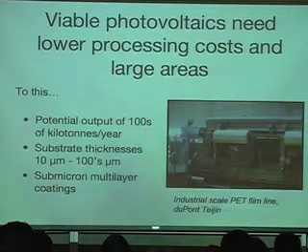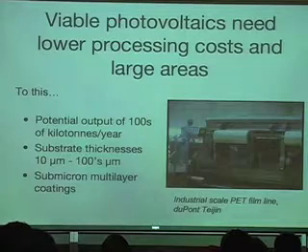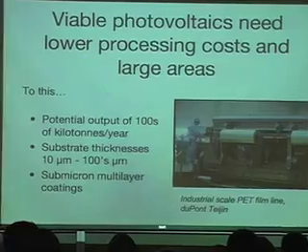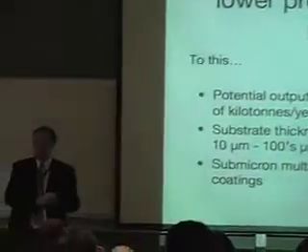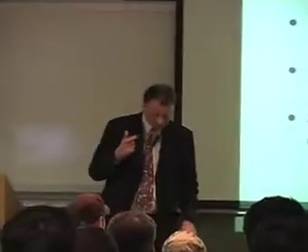One needs to move to processes that are very large scale. Now, we have many industrial processes that produce stuff over very big areas, quite sophisticated things. You look at the humble chip packet, as I believe you call them in the South Atlantic. They're quite sophisticated. It's a polyethylene terephthalate base, a metallized layer, probably some barrier layers to control the gas diffusion properties, probably one or two adhesion control layers, all of these sub-micron layers, produced over massive areas at virtually no cost. So this is what we need to do for solar energy.